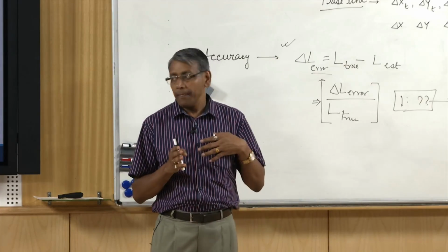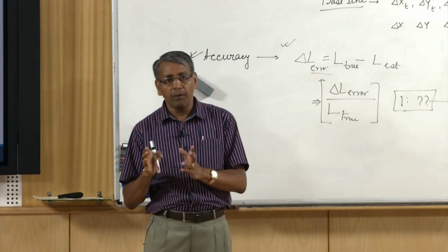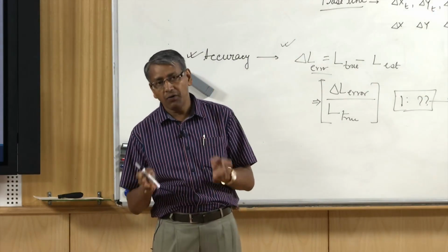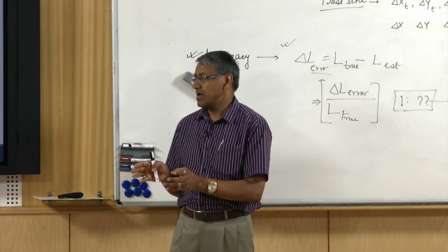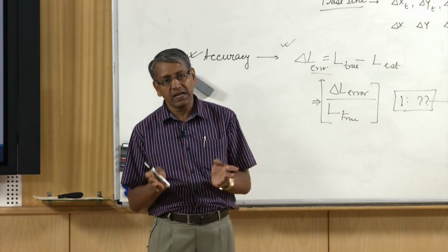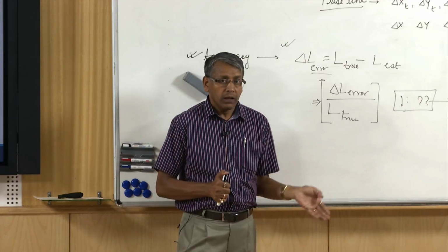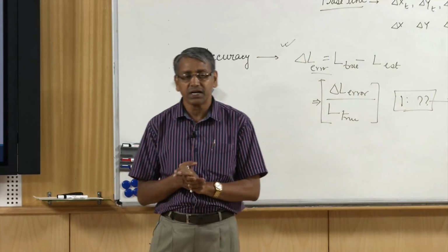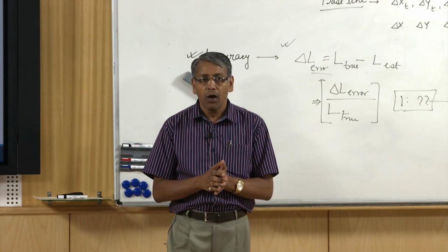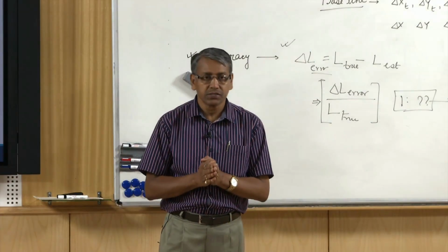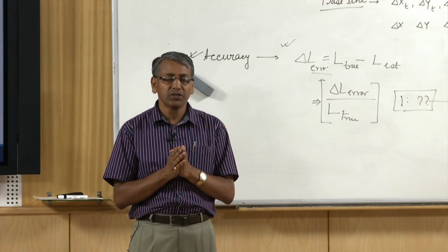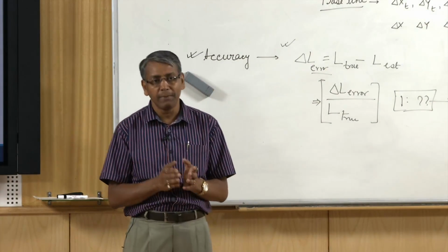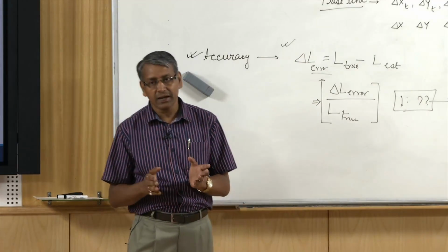In general, that varies from place to place or organization to organization. However, the FGCS standards may be taken as the general standard. The FGCS has considered the 95% confidence level as the basis for its standard, and for point position it is the root mean square error, and for the baseline it is parts per million which is taken as the standard.